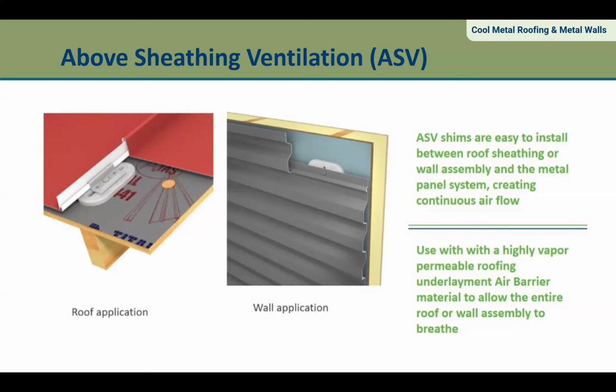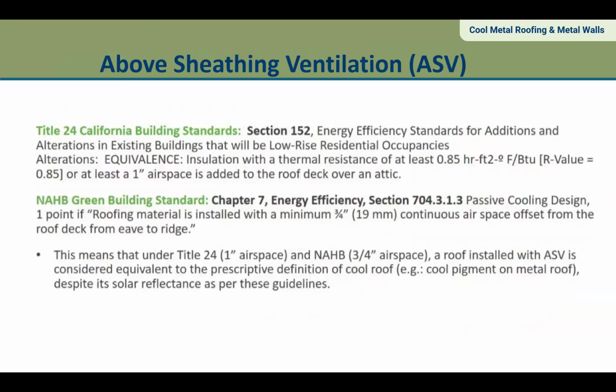And like in the wall technology with weather resistant barriers, you are seeing underlayments in the roofing world become more and more semi-permeable or fully permeable as well. Allowing the vapor coming from the inside of the building to escape, and not trapping it with a metal roof panel right on top of it, is a really great feature.